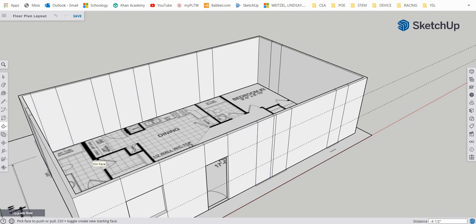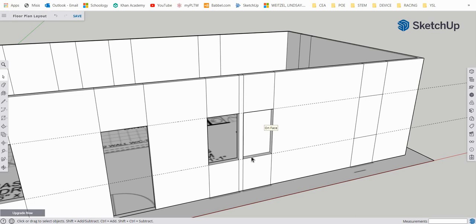So as I'm doing this, I'm realizing sometimes it will leave an absolutely super thin push through. And what you can do is just select the plane and hit backspace and it'll go away. So when I'm going push and I get that one face right there, sometimes when you drag up or left or right, it will give you that. And then you see it doesn't cut all the way through. If that happens to you, just select inside, double click, single click, and hit backspace and it'll cut right through.